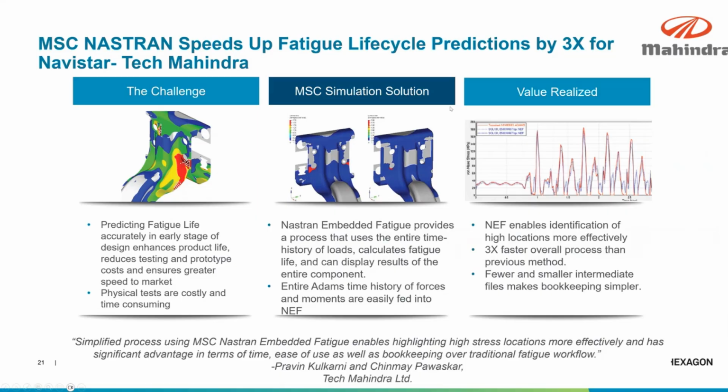Some examples of how some customers are taking advantage of running Nastran with integrated fatigue analysis. I mean, we're talking about models that are incredibly big, and getting any stress results on a car that is like 10 million elements is an absolute nightmare, right? Let alone then post-processing them for fatigue analysis. And CAEfatigue integrated in Nastran delivers the opportunity to avoid that cumbersome process of exporting this large number of results.